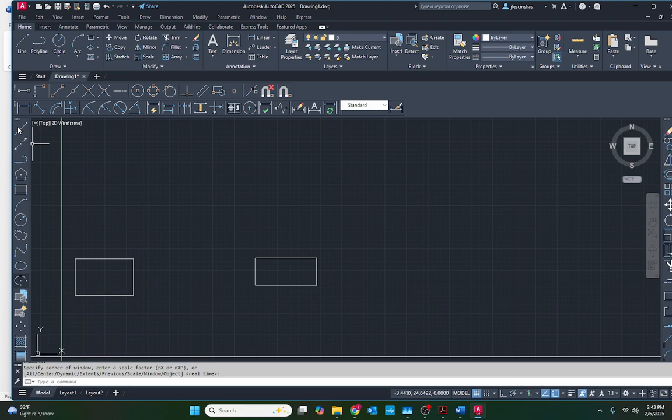So when you click on a line, the first thing you see is this text box, and it asks you to specify the first point. Well, the first point that you specify has to be with respect to your origin, with respect to our 0, 0 that we have down here. And I'm going to start a line right at 0, 0. So I'm just going to type 0, 0. And you can see we started a line, and I can move my mouse and put the line wherever I want.